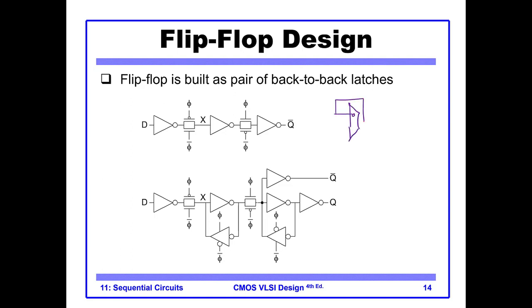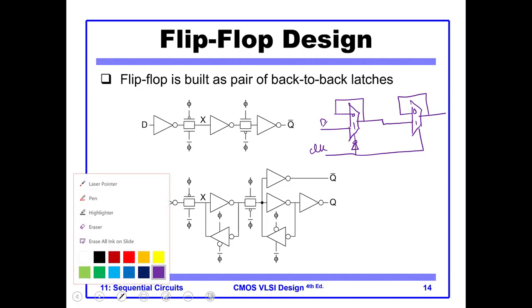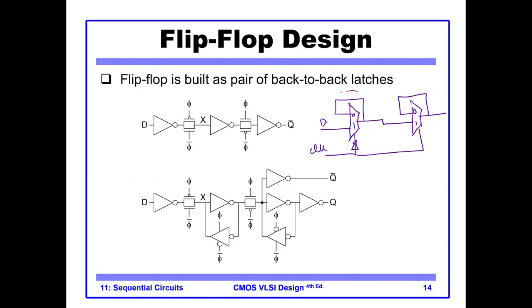So we had this D latch, and we said that if we combine two of these, so this is our clock signal, here we put an inverter, here no inverter, and this is our master, this is our slave.